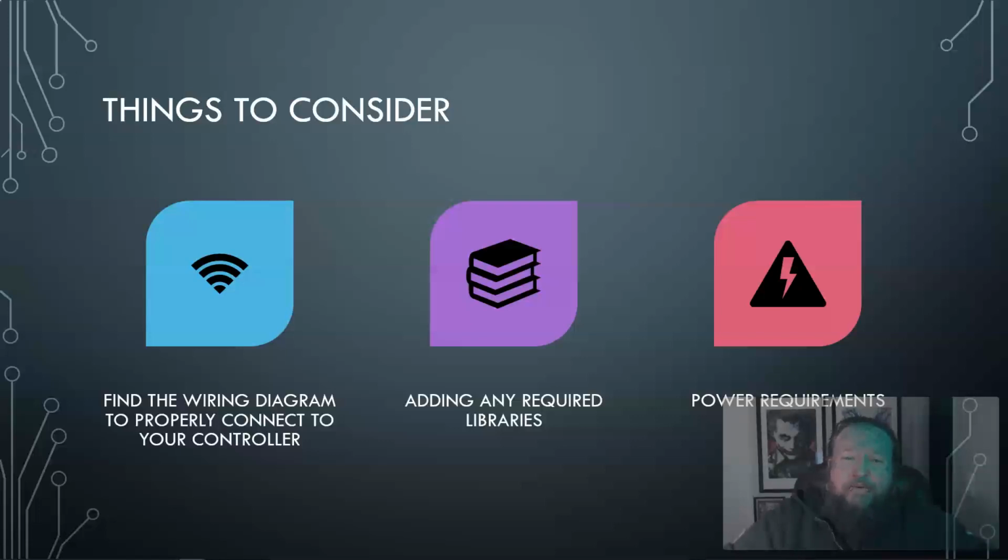And then power requirements. Like, how much power is it going to need? Can it run from what the Arduino provides? Or should you be looking into hooking up a separate source of power just for that sensor that's independent from the actual Arduino itself?